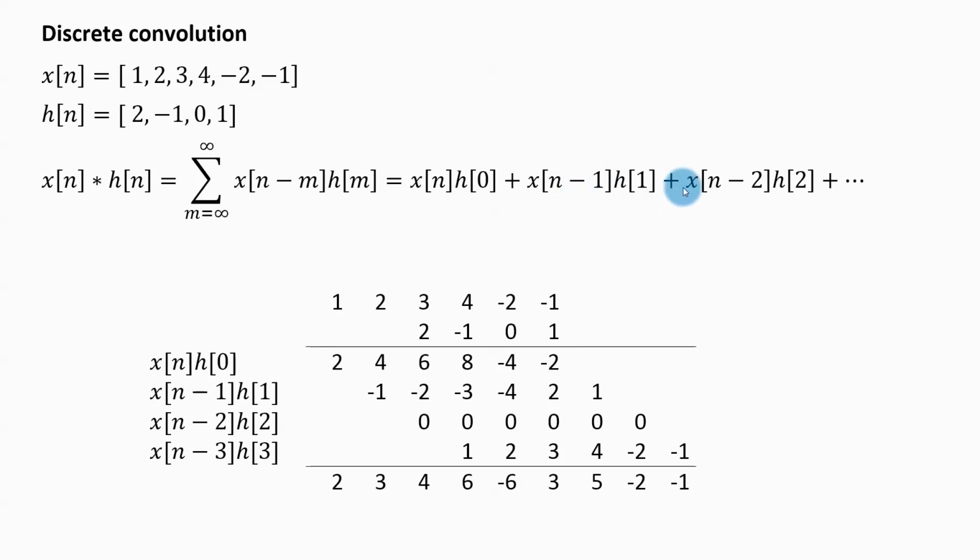Here I have my signal delayed by 2 samples and I multiply it by H2. Again, I have copied that here, my signal delayed by 2 samples multiplied by H2. So I take my signal and multiply it by H2. Very simple, this is 0. So the result is just zeros, and I must not forget to shift it by 2 samples against the original signal.